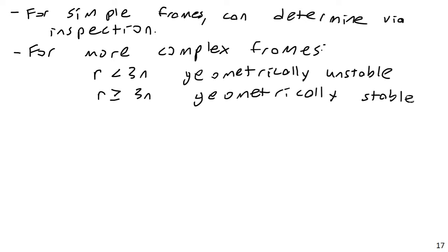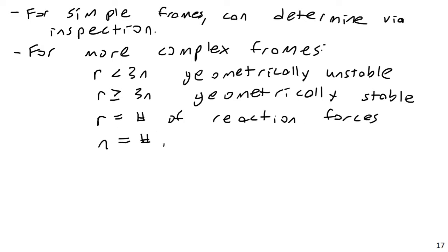Again, in case you don't recall or haven't seen the previous video, R is the number of reaction forces, including any internal forces revealed by cuts. And n is the number of pieces that the frame is divided into for analysis.